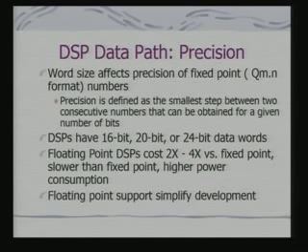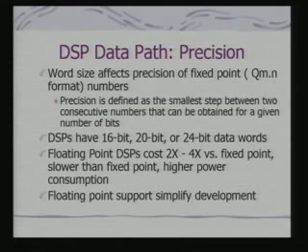On the other hand, you have got floating point DSPs as well. Obviously, floating point DSPs, hardware wise, will be more complex, their cost would be more, and in many cases they are also slower because of clock speed restrictions, and they will obviously consume higher power because you are having more hardware on the silicon real estate.